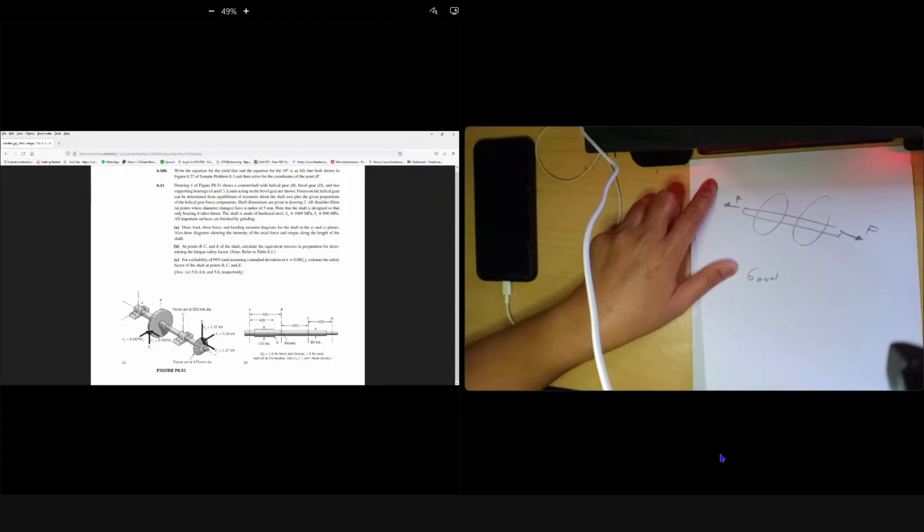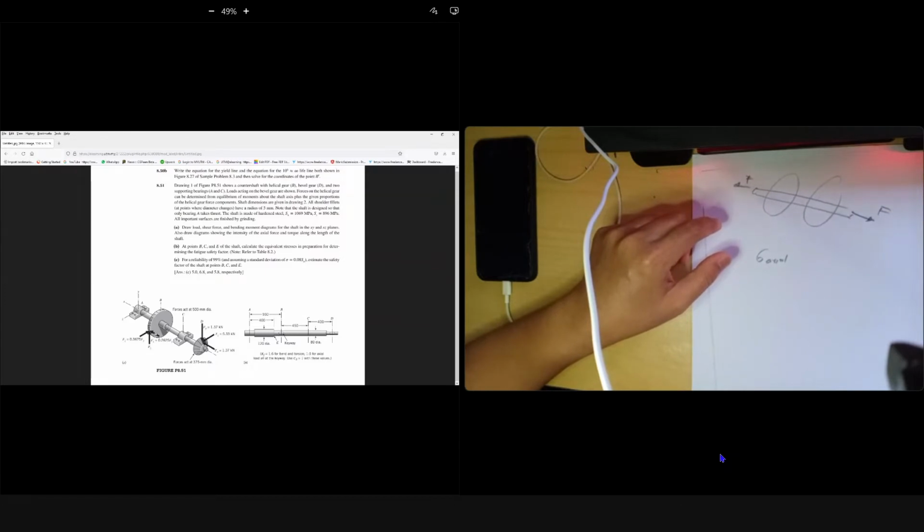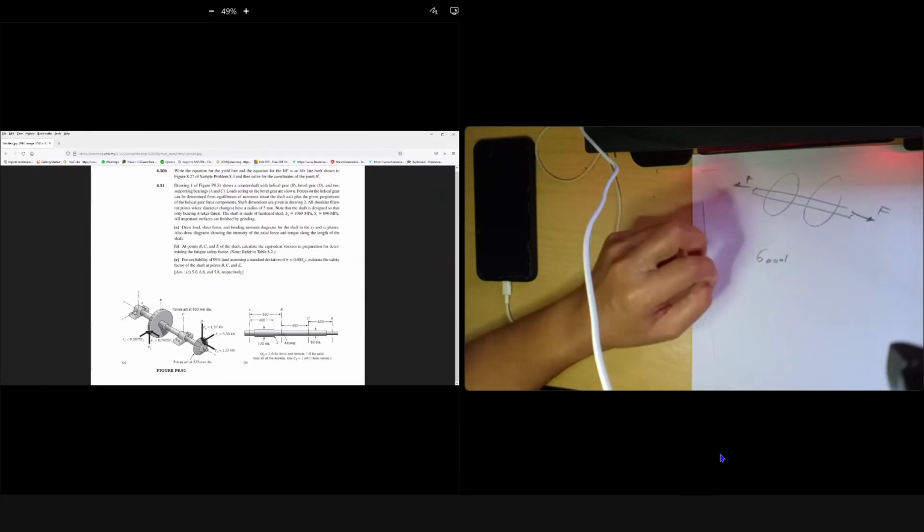But in the axial force diagram from D, C up until B, the value of axial force is only 1.37. Until it reaches point B, you have to add this Fx. So we have about 1.42 if I'm not mistaken. This one plus this one gives 1.42 axial force. So from B to A, the axial force is much bigger.